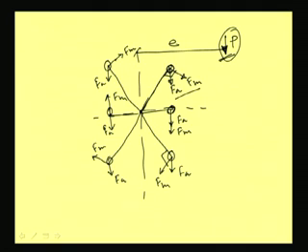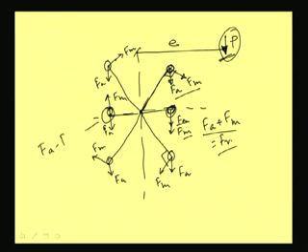For this case we will see that the total force becomes F A plus F M, equal to the resultant force F R. So, it is going to add, whereas in this rivet it becomes F A minus F M. So, the force is going to reduce, whereas in the other case the force is going to increase.